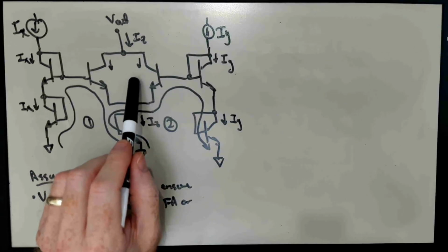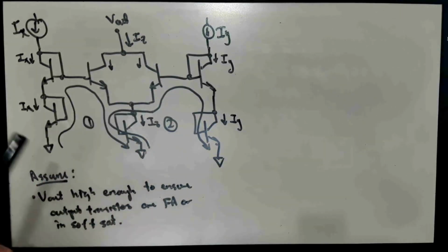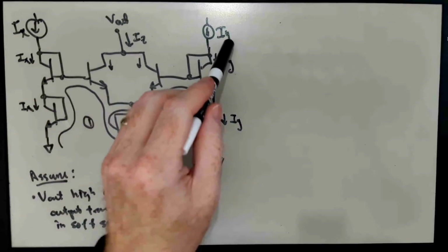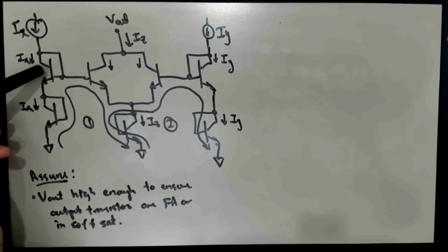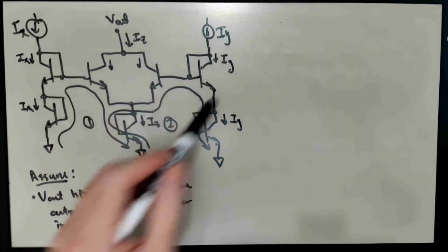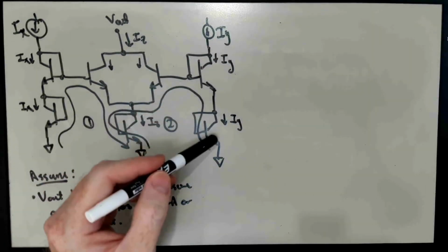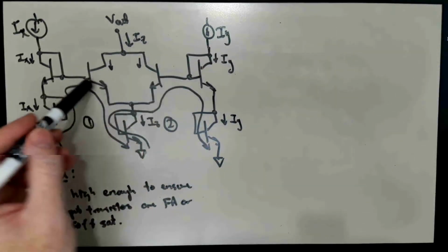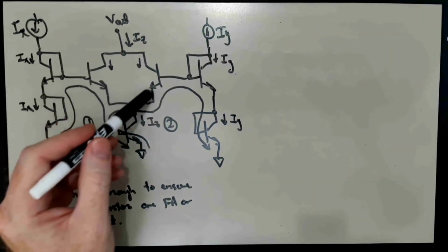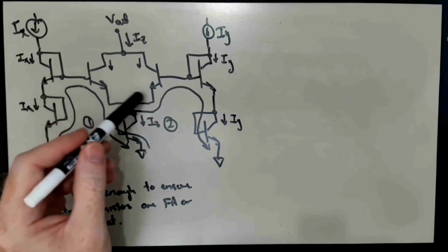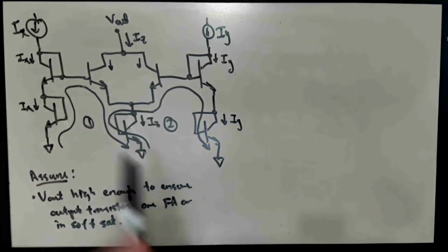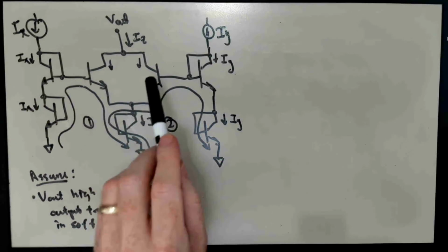And that's going to be true at one point, at the point where IX and IY are the same. When IX is the same as IY, then the voltage that I need for one of these transistors to produce IX is the same as for this transistor to produce IY. And so 2 of those is going to equal 2 of those, and I'm going to have the same voltage here on each of these 2 BJT's bases. And since these are tied together at the emitter, they've got a common emitter node here, then the VBEs of these 2 transistors would be the same only at that point when IX is equal to IY. So in general, they don't split 50-50.